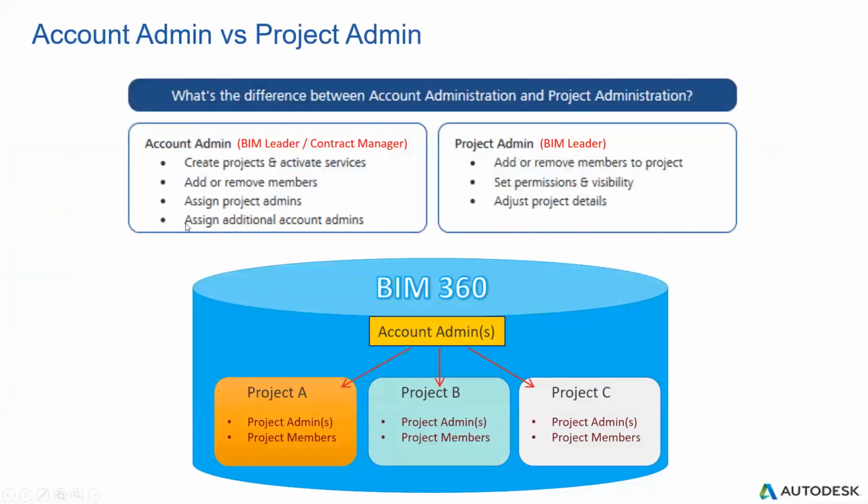Actually, let me explain the structure of BIM 360. Assume this is BIM 360 for our company, which, for example, is named Autodesk. This is the Autodesk BIM 360 Hub. Under it, we have the account admins. I am the account admin because I have to create different projects, and different projects can have different project admins. Project admins can help me assign or remove members and manage all the permissions or documents inside the BIM 360 site.